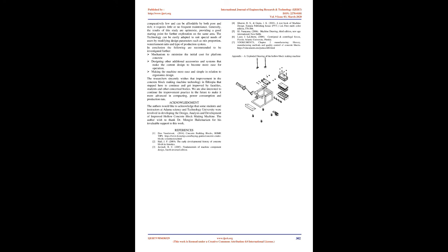3. Conclusion and recommendations. The concrete block making machine is designed to produce 4 blocks at a time. It can also produce 5 blocks at a time by changing the mold and tamper assembly to the desired dimension. On the design, in addition to the compacting vibrating system, the weight of the machine is considered in relation to the personnel for moving the machine and ease of operation. The improved machine is suitable for the production of hollow blocks inside of halls and outside, just a leveled concrete floor is needed.